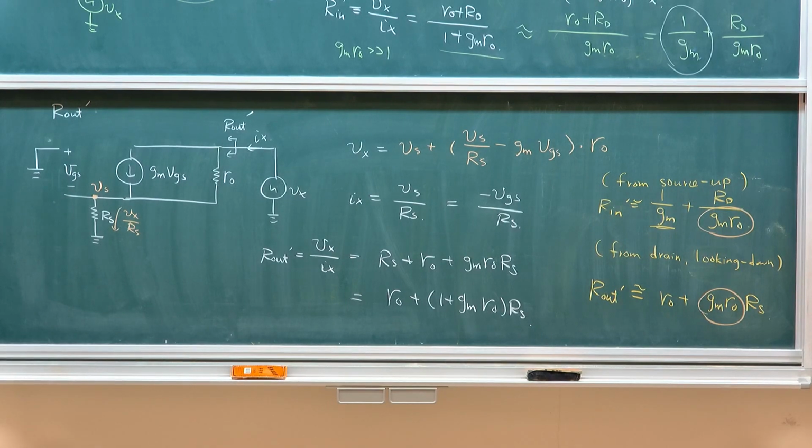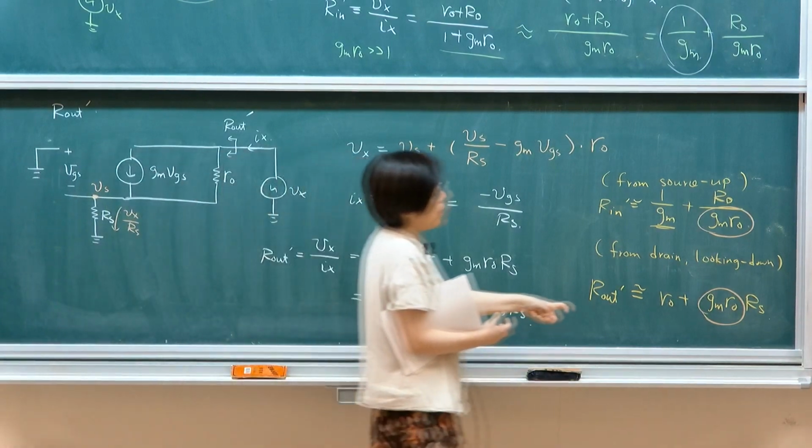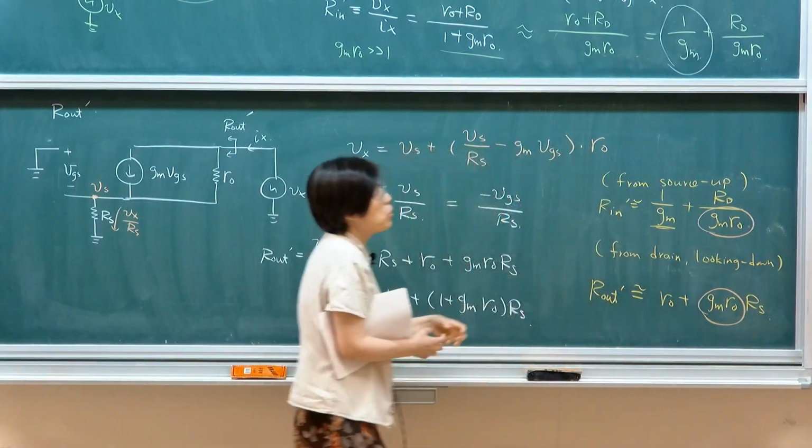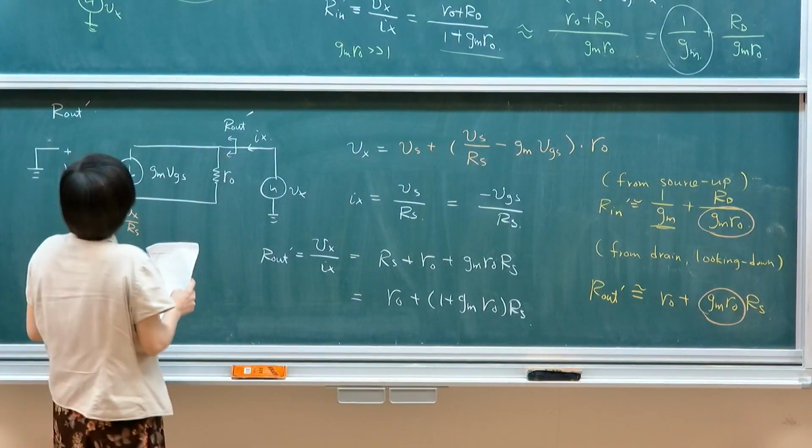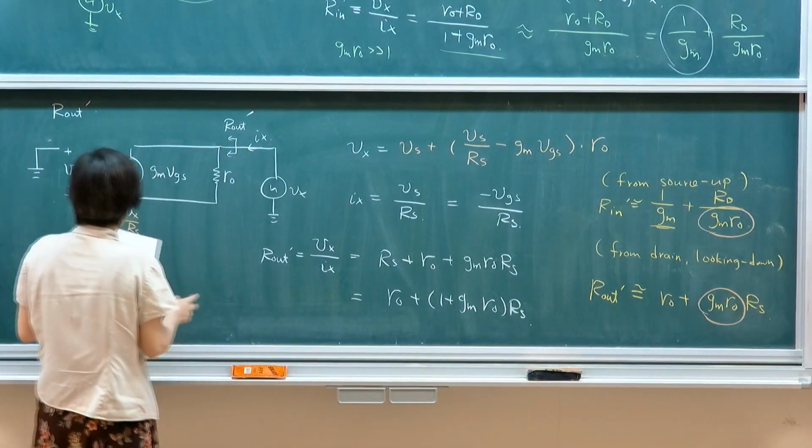This relationship is very useful when we have multiple transistors stacked together. We're going to talk about that type of structure, what we call a cascode. It's like a totem pole. You have multiple transistors stacked together, and these effects will play important roles when analyzing its overall gain under different operating conditions. Okay, so let's do a summary as well.